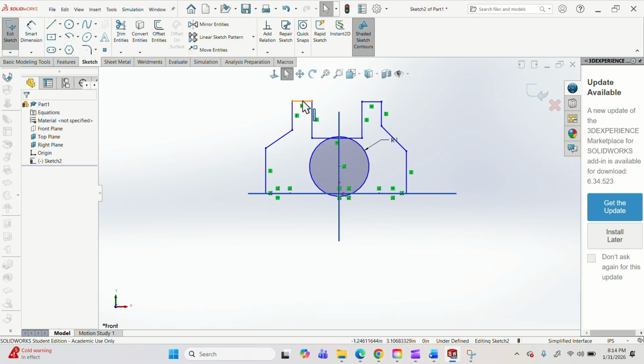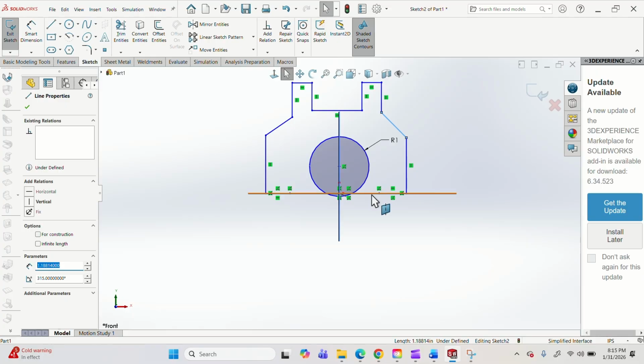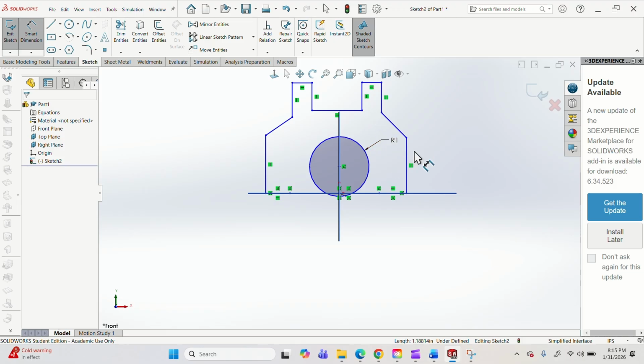I was actually talking to a buddy of mine today, and one of the first things he reminded me of that I should mention, so thank you, Matt, was when you do a rough sketch, once you start putting dimensions in, especially like how that one did, it'll start blowing up and throwing things out of proportion. One of the things you probably want to do first is throw an overall dimension in there. That's like your biggest dimension, right? So everything else shouldn't be out of whack or proportion unless you gave it the wrong dimension.